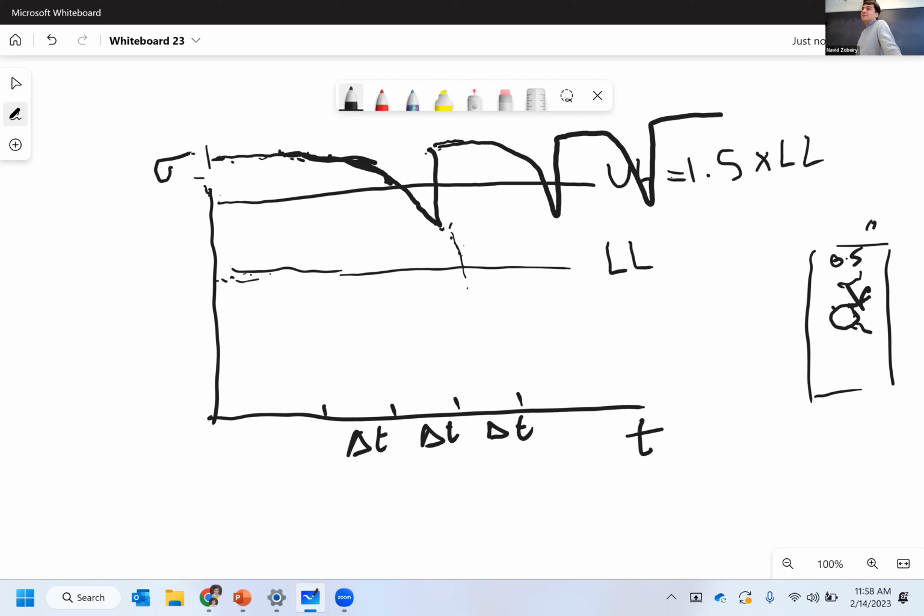You do fatigue tests. You characterize the fatigue properties of the material, so you know how fast it grows. So you know exactly in 3 months' time, how much maximum would be the length of a crack. In 6 months' time, in 1 year. You wouldn't let the crack grow significantly such that the structure cannot carry limit load. So you will catch it before that. So you set your frequency such that none of the cracks are large enough to reduce the performance of the structure below the limit load. So that's the mentality behind designing metallic aircraft. We're going to go over the proper terminology, but it's understanding the growth and fatigue, setting the proper inspection time, repairing it, bringing it back up, and doing it again and again and again. Right. So that's for a metallic structure.